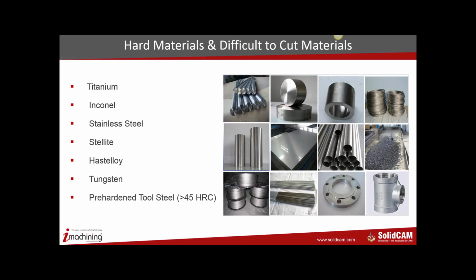It has extremely high chemical reactivity, so it gives this unique edge buildup on the tool. And once the edge buildup starts on the tool, trust me, in the next minute you're going to have the tool completely disintegrated. On the other hand, Inconel is a pretty sticky material. So the wear mechanisms of the tool undergo dynamic changes.